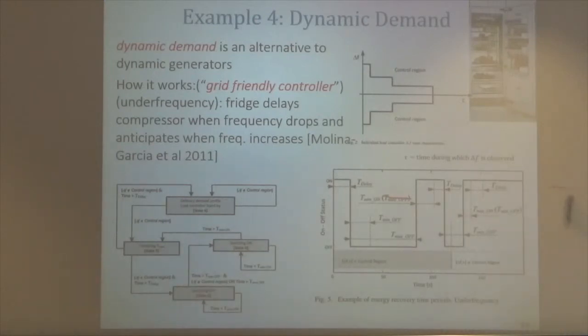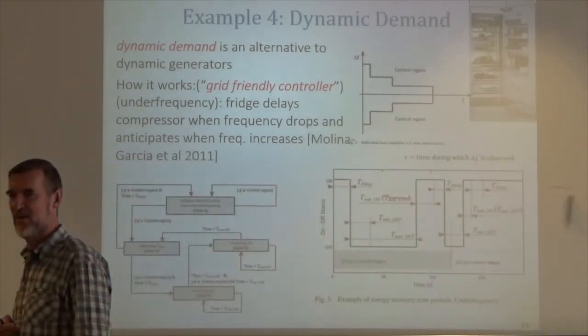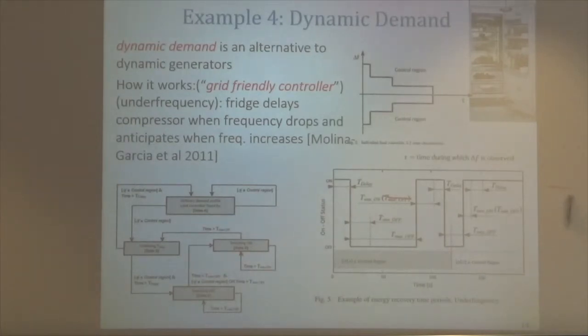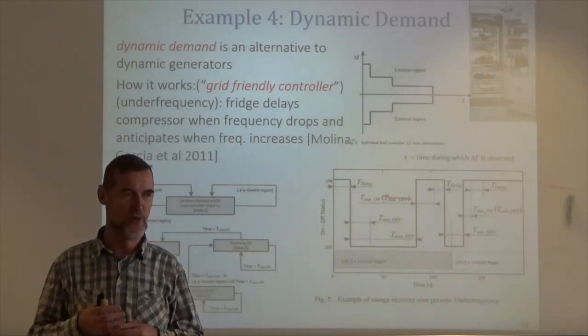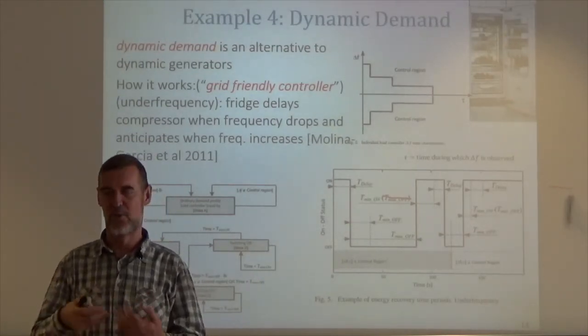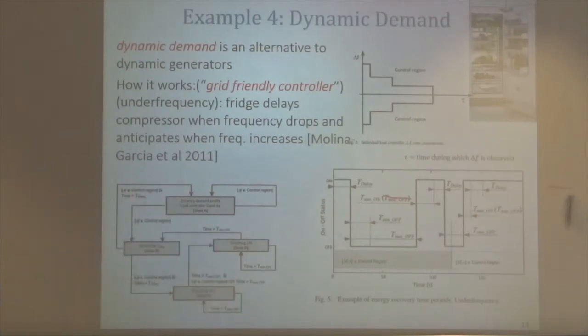They have a higher time constant, like even if it goes off before it gets hot, it stays so hot. Exactly. So first you can play with them because your fridge is a thermostat-based system. So it's like David's house, that there is a temperature band. The optimal temperature is 4 degrees, which means you should not increase above 4 degrees, but the temperature in the fridge can be anywhere between 2 and 4 degrees. So you can store some cold, although thermodynamically it doesn't mean anything, you can store some cold in your fridge to anticipate a period of higher energy demand, for example.